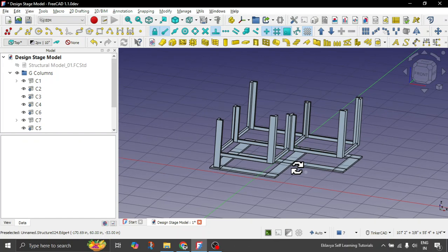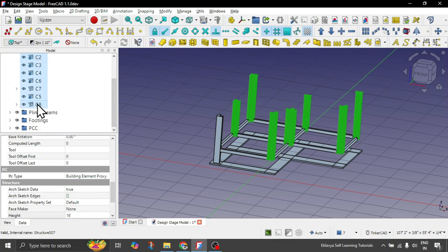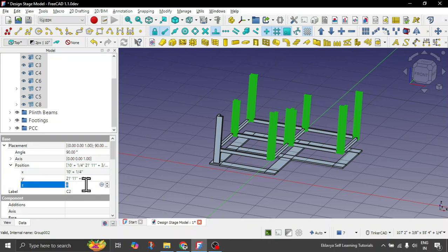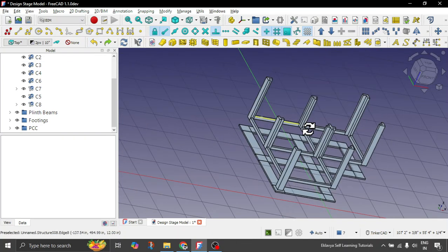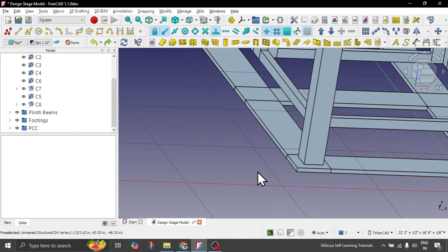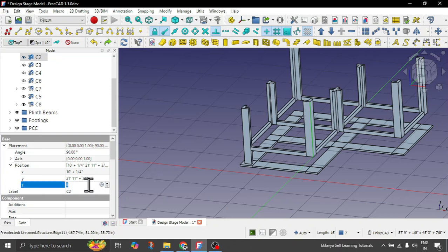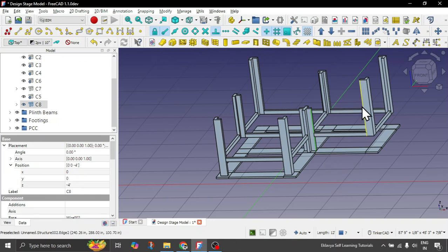So what we need to do is position all of the rest of the columns also. Yeah, this is the approach which we should avoid, because the coordinates take common values for all the columns when done at once. So that's not a problem. We'll quickly offset every column. Set this one to -4 feet. This one, -4 feet. So the height, you can see it's adjusting for the clones, and for the others we'll do it quickly also.